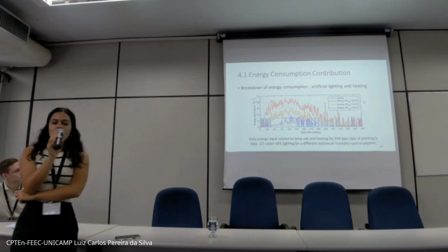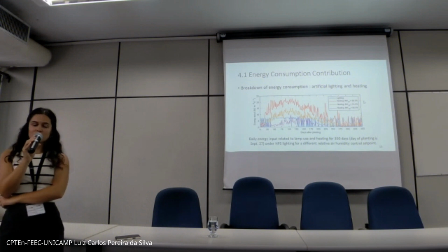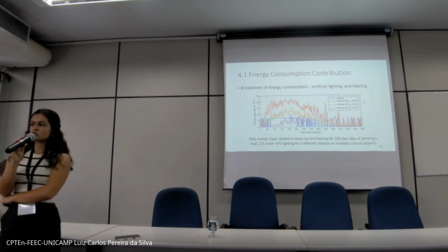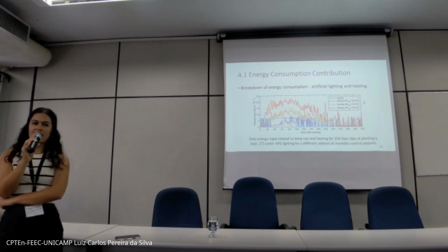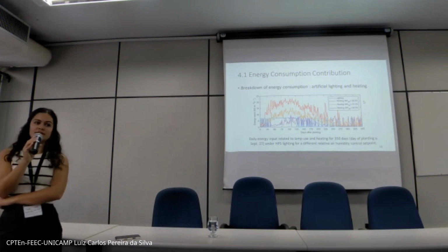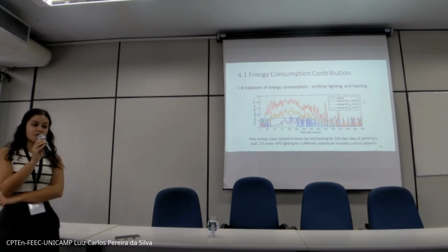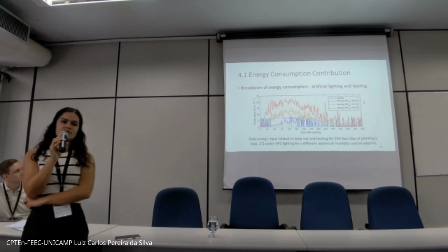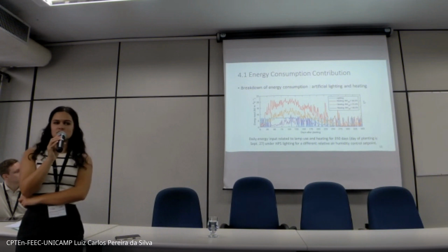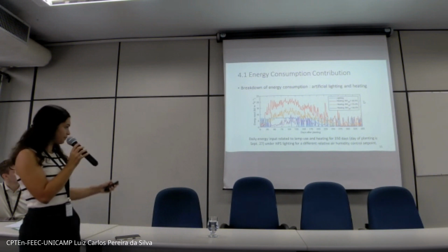And this is because when we want lower humidity in our greenhouse, one of the ways to achieve that is to open the windows to get the humidity out. But if we're during winter and we open the windows, then we have to heat our greenhouse way more. So it's not advantageous. But in a certain way, we cannot go over a certain amount of humidity because it's not good for the plants. But we still want to maximize the higher humidity we are able to have.